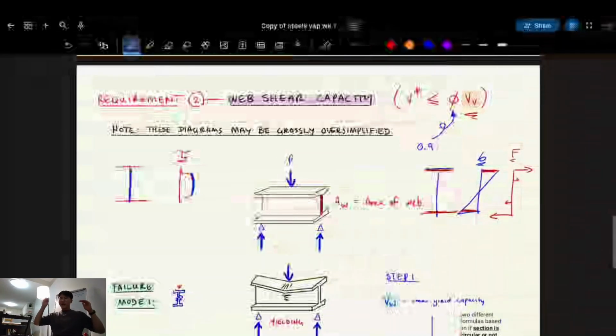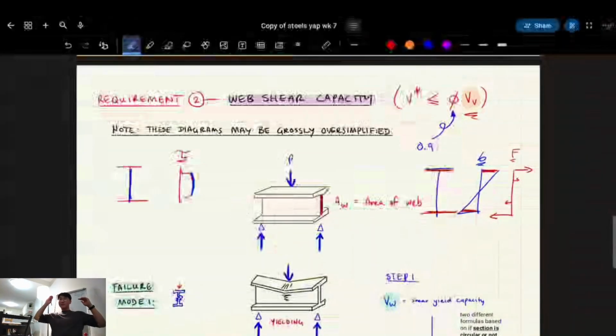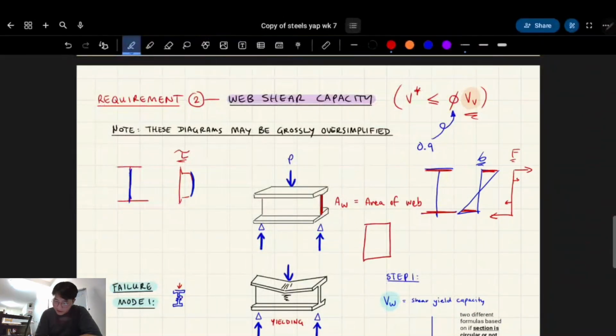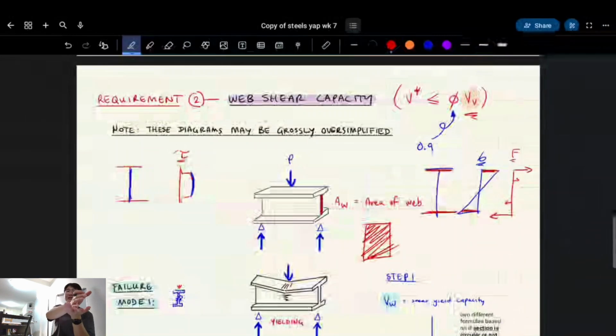So an I-beam is super optimized because the web takes on the shear and the flanges take on the bending. It's cooperative action, which is why it's far more optimal than a solid steel section. You have these specialized parts, the flange and the web, that do different things, so you get more bang for your buck.